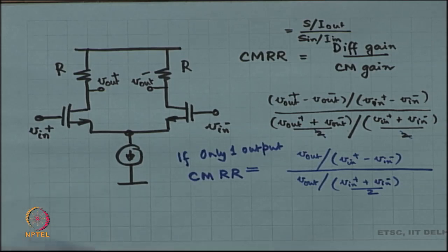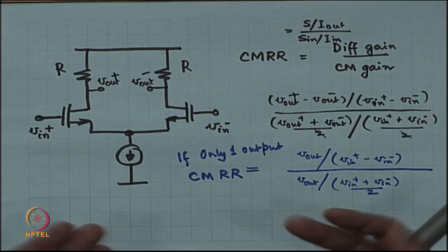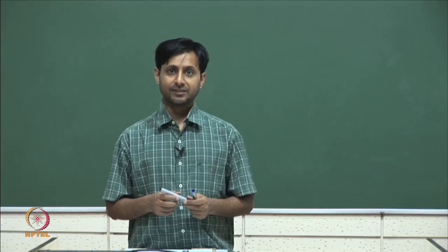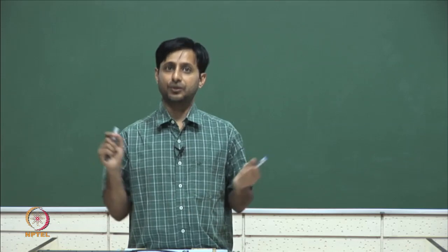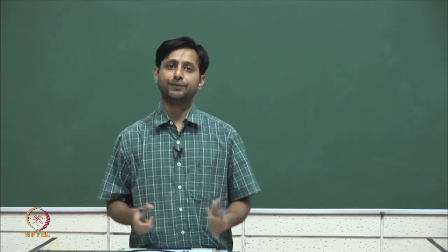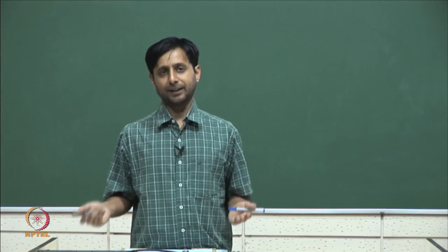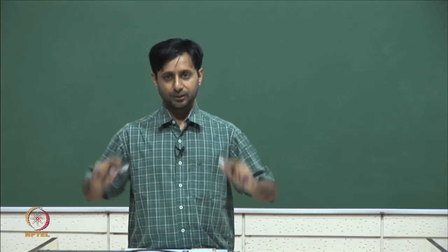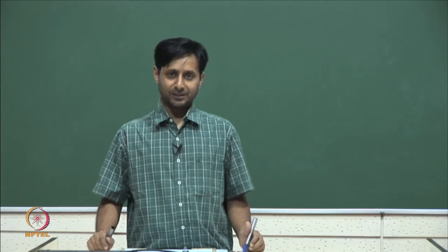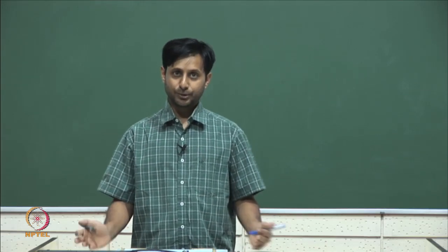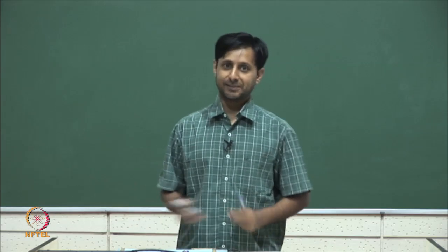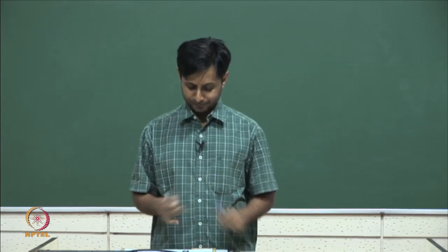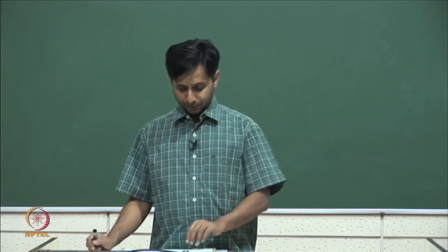Now, when you find these common mode gains and differential mode gains, you have to do the superposition experiment. You have to turn off the differential mode signal to find the common mode gain, and if you are trying to find the differential mode gain, you have to switch off the common mode signal. So, be careful, do not have both running and then expect some nice answer, it is not going to work out. So far so good.